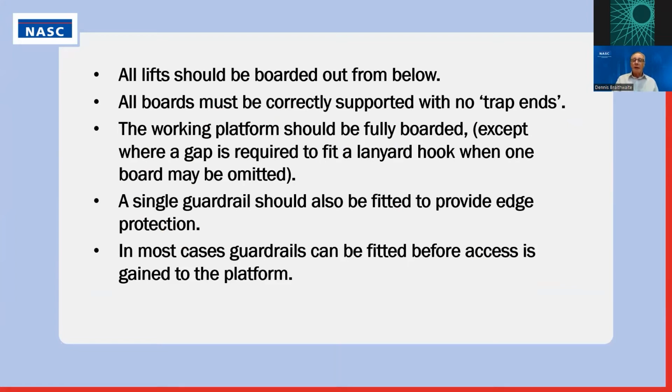All boards must be correctly supported with no trap ends. Working platforms should be fully boarded. Slight exception to that is if you can leave one board out in certain circumstances, if you need to be able to clip the lanyard hook to the ledger below. A single guardrail should then be fitted to provide the edge protection. And in most cases, the guardrails can be fitted before access is gained to the platform.